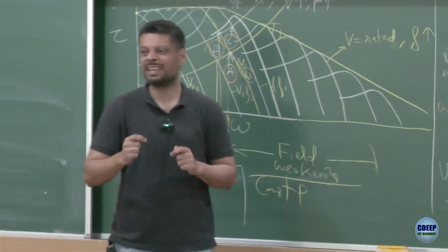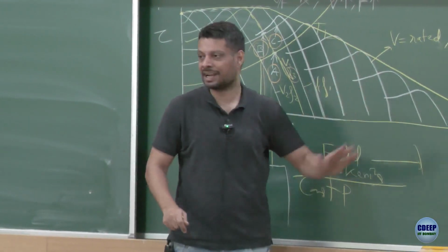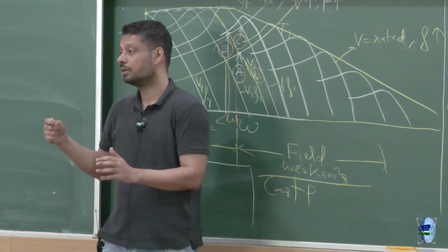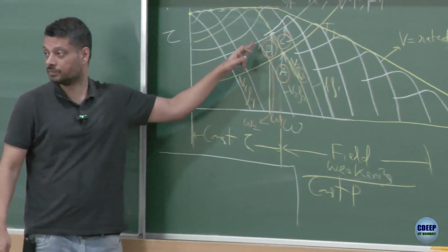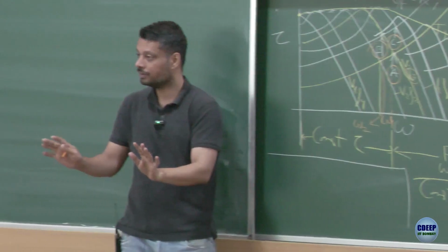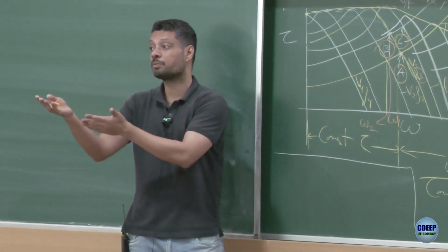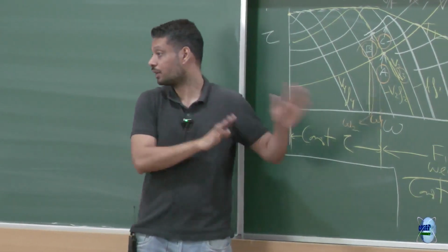Why we are not doing exactly the same thing is because of two reasons. At this point here we are mostly looking at steady state speeds. We are not so much looking at the overshoots. But in reality everything matters. When you turn on these two more bulbs, do you think you go from speed 1 to speed 2 and just settle there? No. There is going to be an overshoot or undershoot. But we are not getting into those things. This is what you are probably learning more there, and you are learning how to tune the PI controller to do that, which we are not doing here.